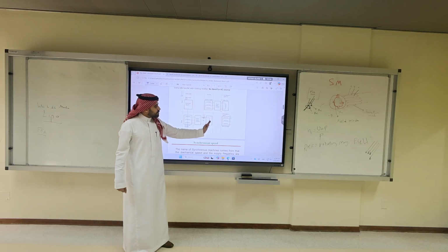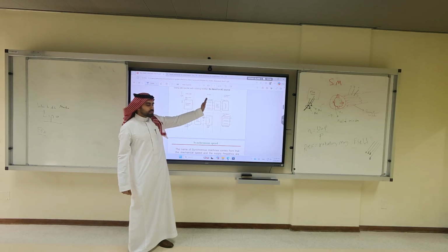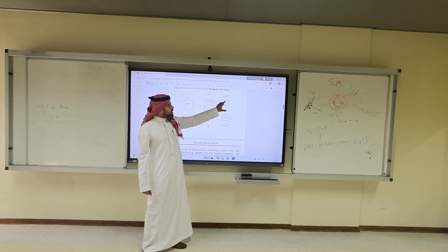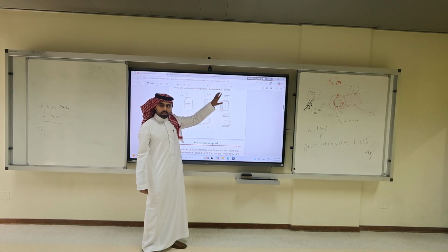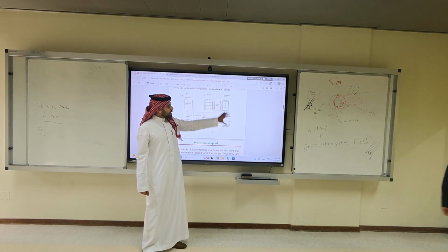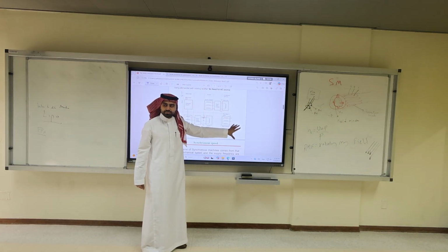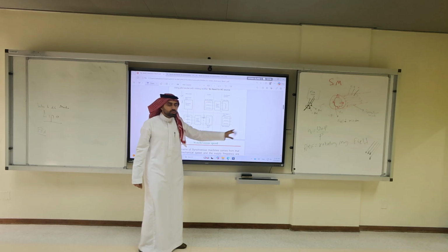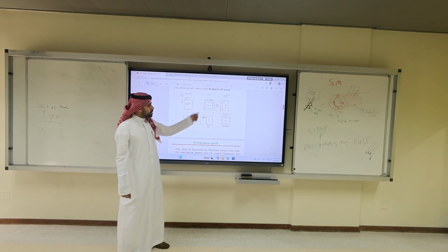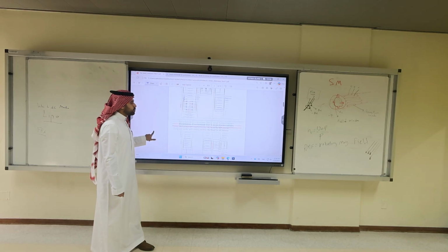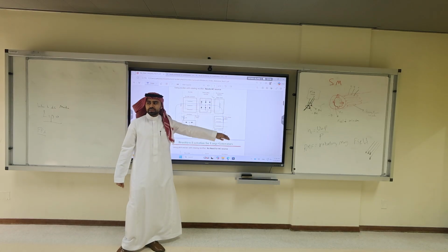Now I'm at the stator. I apply three-phase AC on the rotor with another group. We call them the exciter armature. Then we rectify to the main field. Once we rectify the main field, I have big DC on the rotor. Then I can get my three-phase output on the synchronous generator. So here we went rotor, stator, rotor, stator. Here we went stator, rotor, stator.